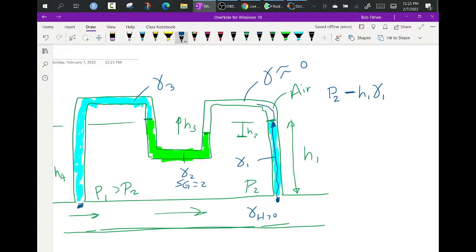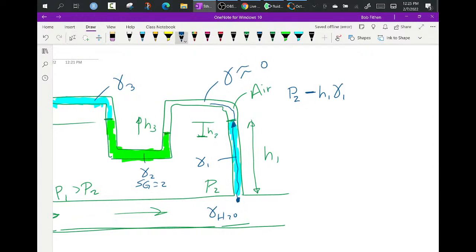Now, the problem is, technically, let me slide over. Technically, this doesn't look like it, but I do go down through air, but this is almost zero. So if you get an air bubble in your line, you can really mess up your pressure reading. So when you're taking lab 2, I guess it is, when you're taking that, what you do is you try to thump it.